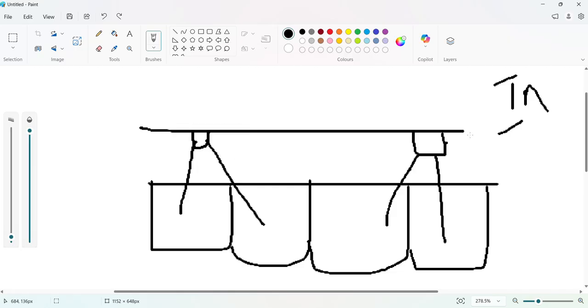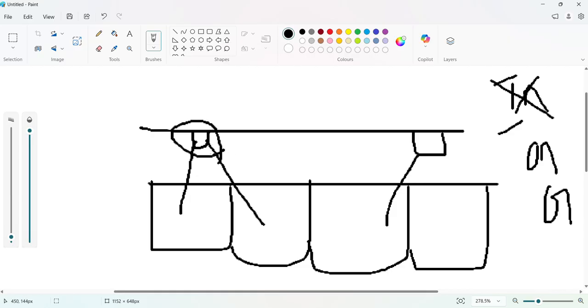If you are adding on grade instead, on grade means we have given 60% efficiency. Do you remember in the design condition we gave 60% efficiency? Whatever water comes from this area, a maximum of 60% will come inside this inlet and travel to the manhole.